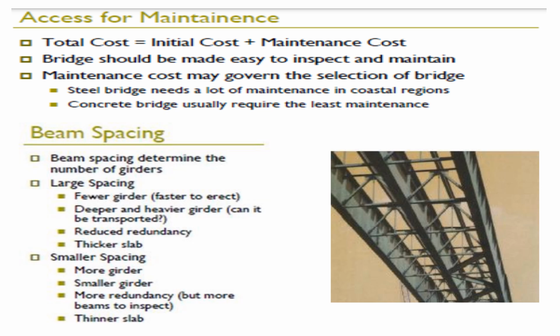And then when it comes to the beam spacing, it determines the number of girders actually. For large spacing, there will be fewer girder, deeper and heavier girder, reduced redundancy, thicker slab, while for the smaller spacing, there will be more girder, smaller girder, more redundancy, and thinner slab.